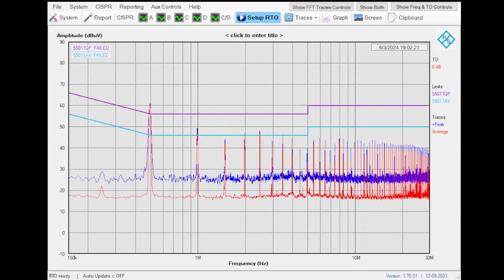failing. Instead of working with the filter in some kind of trial and error, the recommendation is to work with trying to identify what is common mode and what is differential mode. You have the possibility to use an external device that is called LISN mate, or work with a transformer, resistors. There are different methods to do that. But what I like to do many times is to work with the oscilloscope. So let me show you how is the